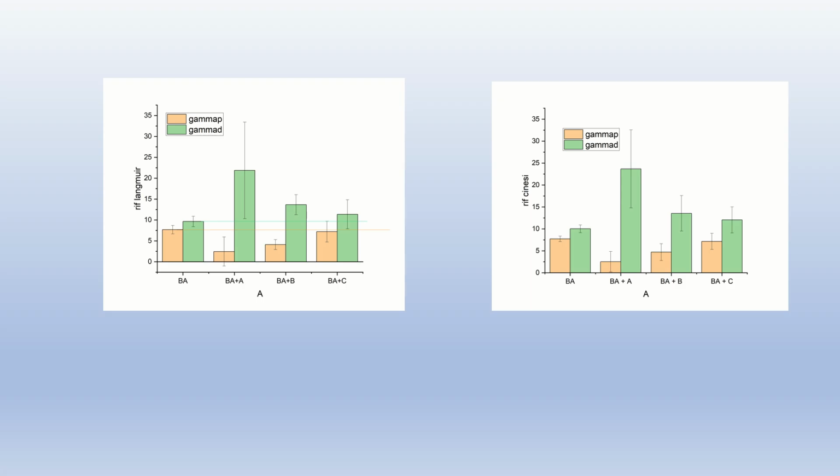In the last slide we show the results. You can observe the behavior of the polar parts and apolar parts of the bitumen. This method, we think, is important to evaluate in the future for warm mix asphalt, because I repeat that warm mix asphalt uses a surfactant, and for this reason we think that the surfactant changes the polarity of the bitumen in the surface.